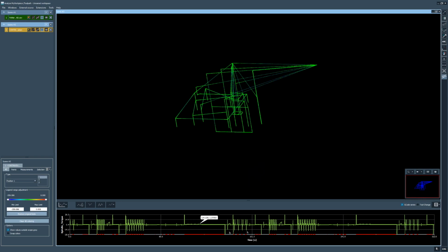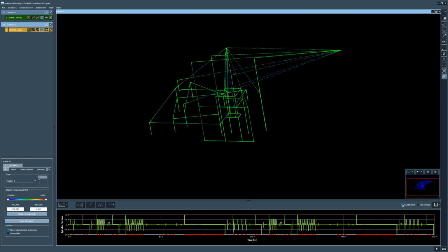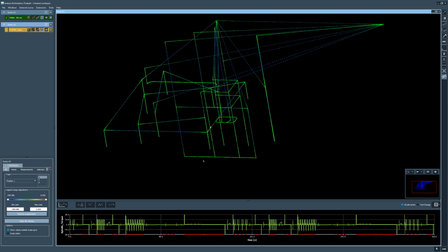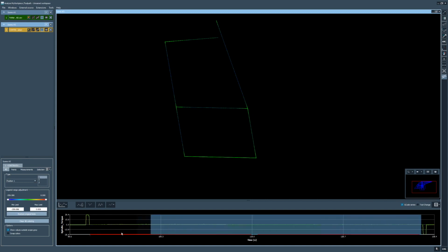And yeah, this can be seen now here. And what we now also see is that here are red and gray areas. And if we uncheck this box here, then they disappear. So what do they mean? They actually show you where are areas where you have a G1 movement and where you have a G0 movement. Or let's say red means non-G0 and gray means G0. And this shows you where the machining actually begins, like the machining on the workpiece.